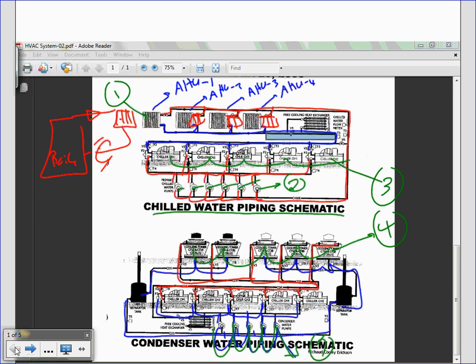Just be aware that when you get into a major system, you separate the mechanical equipment from the lighting equipment and from the receptacle equipment. That's very common. So you have a panel or panels for receptacles, a panel or panels for lighting, and a panel or panels for mechanical equipment, and the main switchgear, of course. And if you have a UPS system, of course, you're going to have a panel or panels for data equipment. So these are, like Phil always says, big chunks of loads.